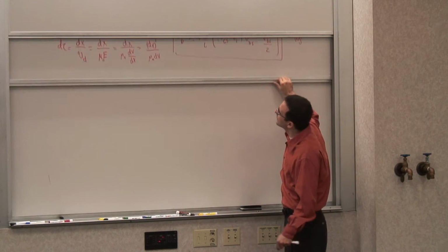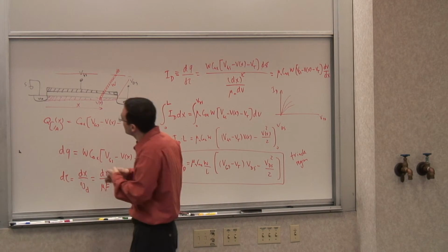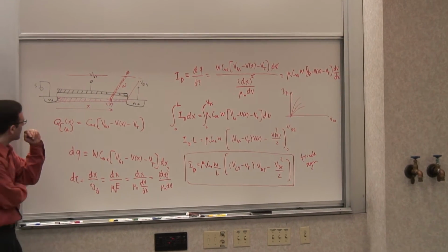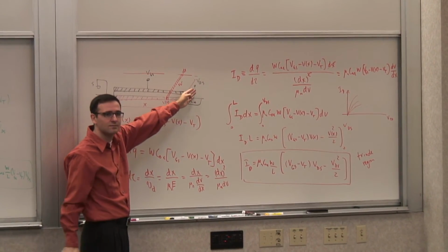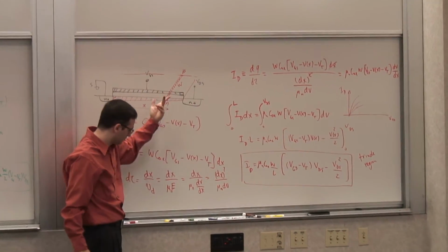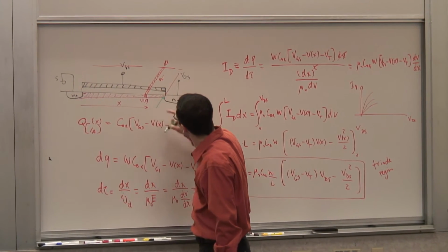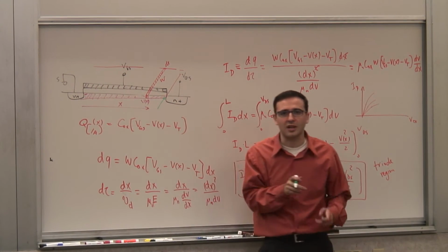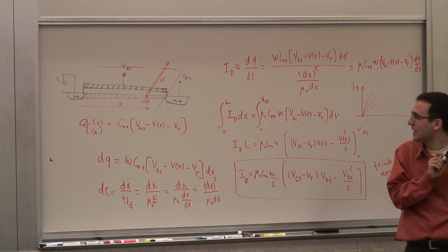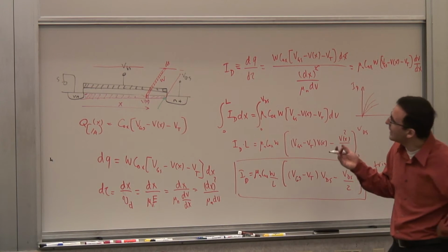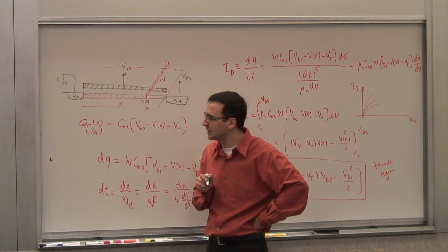But now, for this to hold, of course we have to have a certain condition to be met. So let's look at what conditions we need for this to hold. Now, what happens if I keep increasing my VDS? Let's look at the inversion charge density right next to the drain in the channel, as I increase VDS. So what is that density anyway, in terms of the voltage that I have? Can you tell me what it is?